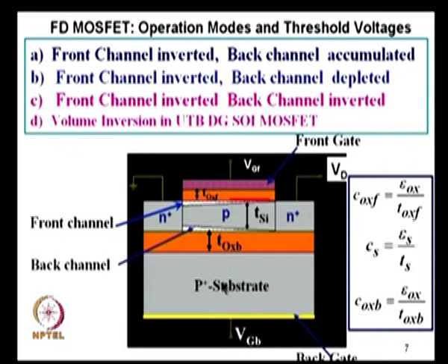To simplify, it will modify it only marginally, with a small drop in the substrate if the doping is present there. Okay. So, when you go to double gate FinFET, the situation will be that this will be heavily doped, and this also will be heavily doped. So, we consider that case, okay, to avoid more complication. In other words, you can say this is a metal here, this is a metal there. There is no drop here in the silicon.